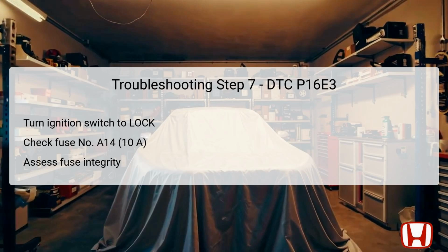If the fuse is intact, you can proceed to the next step, knowing that the circuit is complete. However, if the fuse is found to be blown, it is important to trace back for potential shorts in the +B horn wire between the battery sensor and the under-hood fuse relay box, and replace the blown fuse to restore operation.